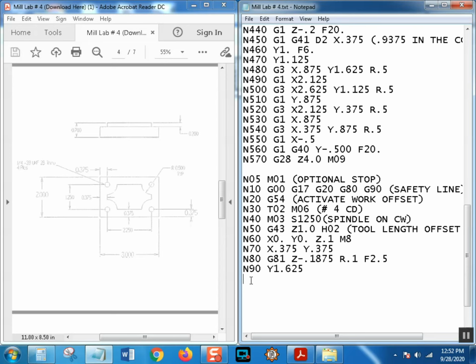All right. So we need another one. And remember, I'm going to resequence these. Now I'm going to do this number. All I have to do is move the x-axis to get over here. Remember, I'm setting at 100 thousandths. I'm right here above this hole. I just drilled it. I'm 100 thousandths above the part, so I can move without hitting anything. So I'm going to go to this one. Well, let's see. That's definitely going to be an x-axis move.